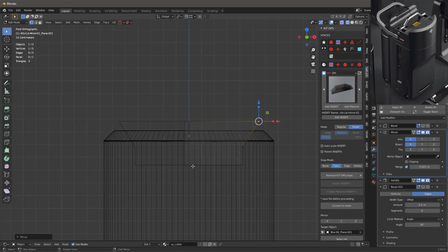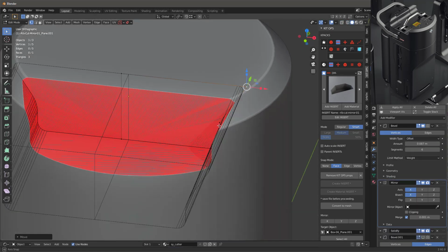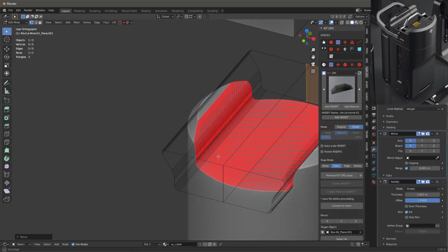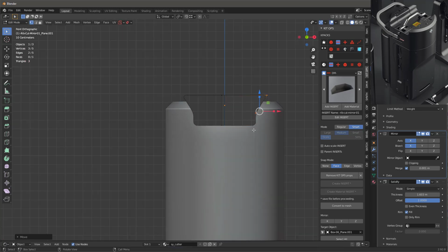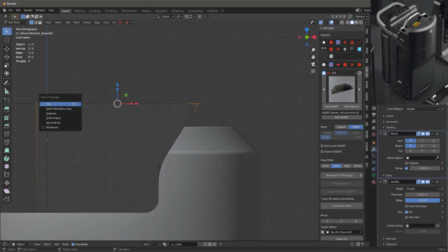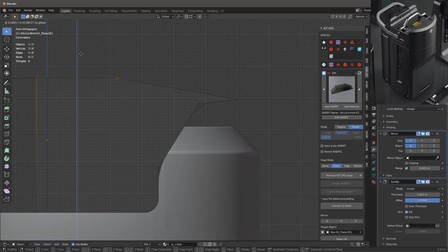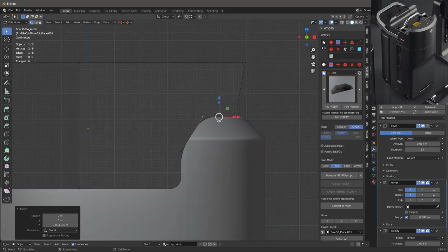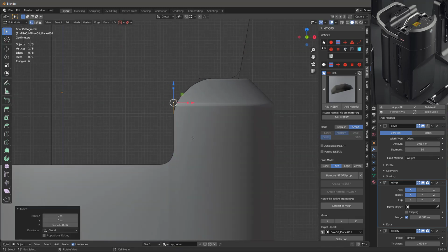Now I'm taking one of the inserts from the minus collection, and it's a mirrored insert. So I'm just editing one half of the vertices here, and it's got bevel modifiers on it, so it makes it really easy to change it. One of the great things about this approach is that you can continually tweak it as you go. And as you see throughout this video, you're going to see me continually change this one modifier because it's critical to the overall shape. So these bevels are critical.